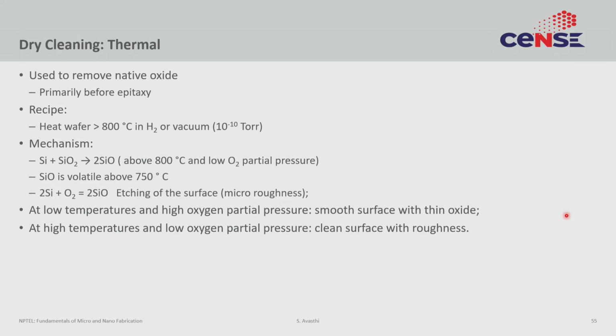You tend to get smooth surfaces with the thin oxide, and if you go to high temperature and low oxygen partial pressures, you do get a clean surface, but then you get some surface roughness. So, there is some surface reconstruction that happens when you heat these things up at high temperature. So, you have to play a careful game.